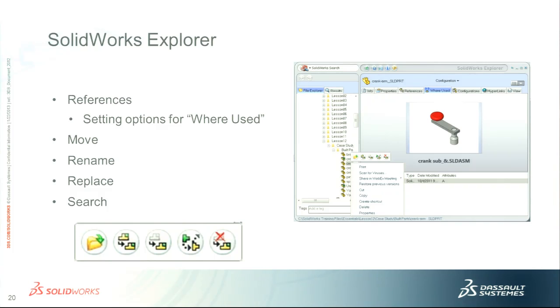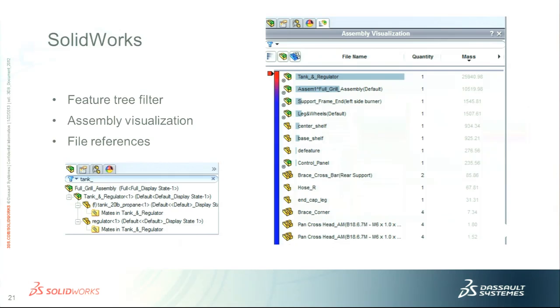You can also do searching with SolidWorks Explorer, and you can also add tags to parts. So there's this field, I'm pointing at it right here, tags. So I can add any kind of information I want for a part file that gets tagged, and that information is searchable. Okay, it just lets you put a tag on your SolidWorks parts or assemblies or drawings.